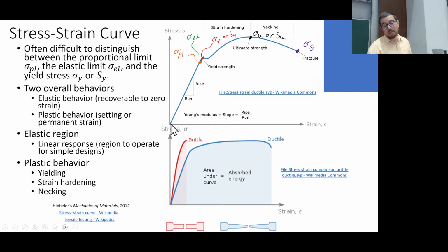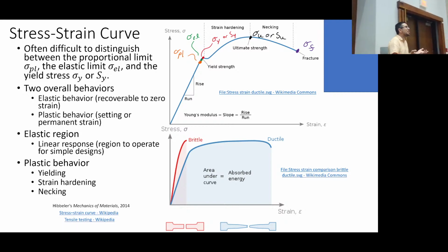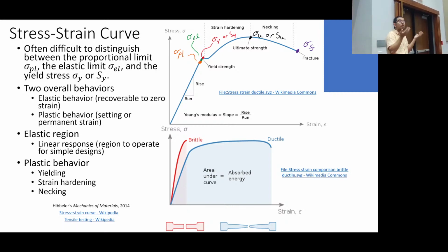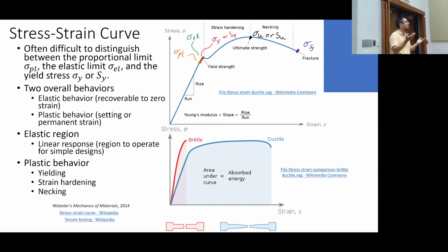And then I'm going to say, okay, minus, right? So rise, I'll do the rise at this one, and the origin, okay? And I'll do the strain here and the origin. Well, the origin is 0, 0, right? So it's just, often, not always, all right, it's often just the yield strength divided by the strain at the yield strength, okay? And that's all you have to do.